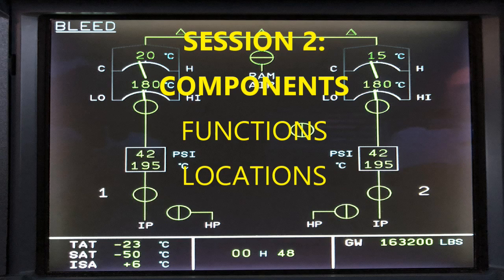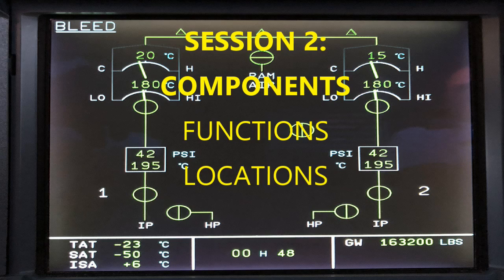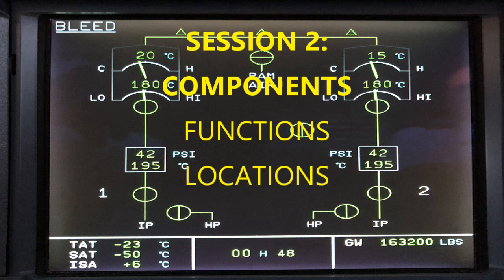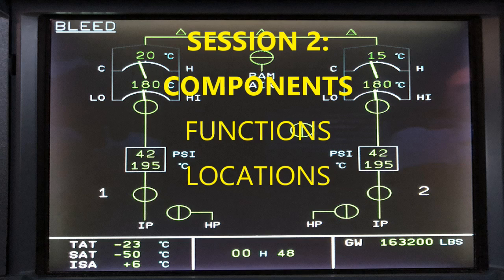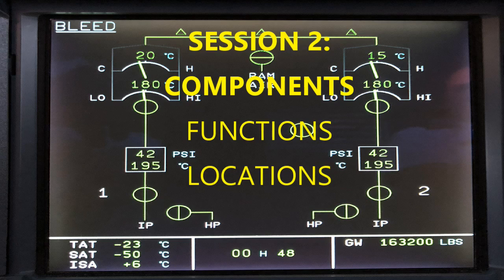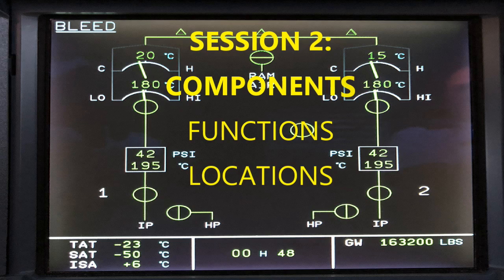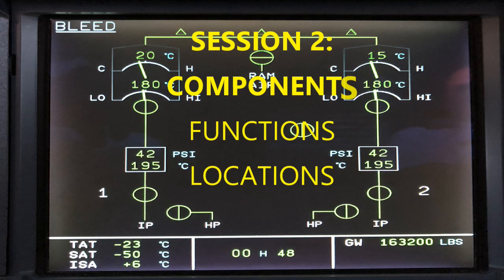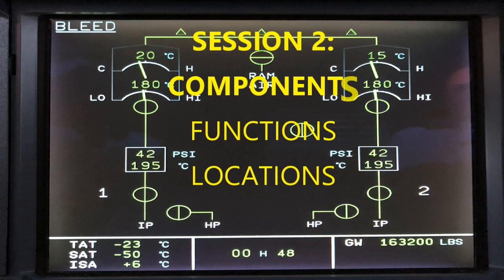And then what happens here with the load valve is, when you have that APU available, you can push the APU bleed push button. There's an APU bleed push button switch on the 25 VU. There's one on the overhead 30 VU, and then you have one on the 25 VU to start that APU bleed air supply.